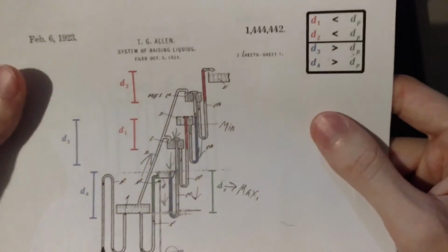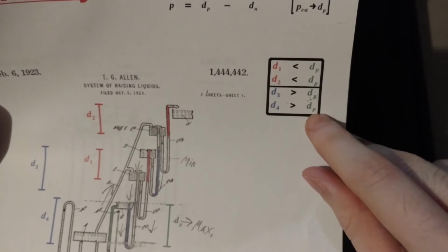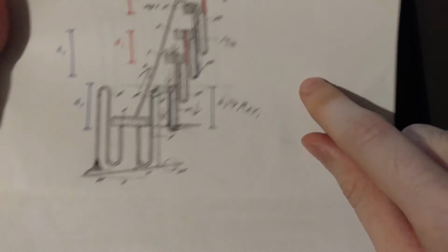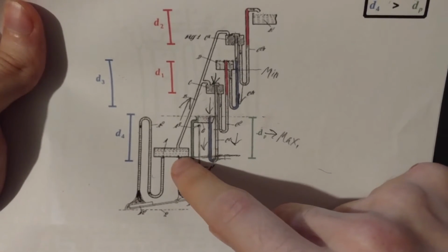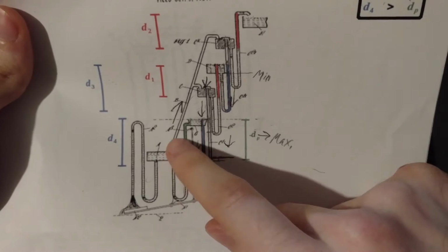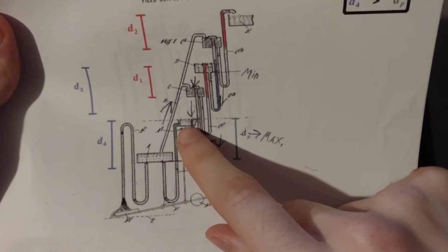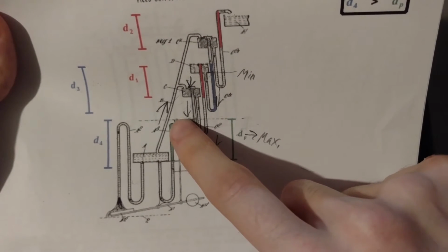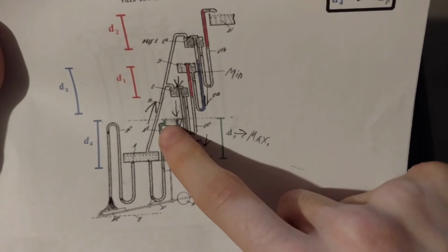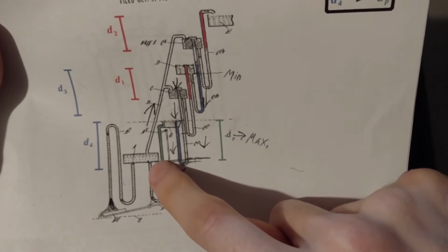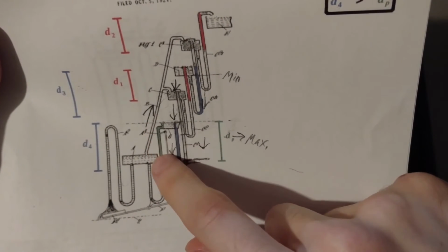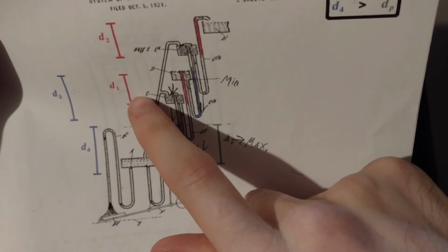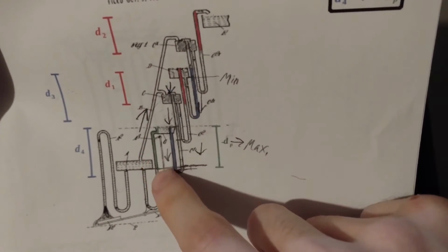But anyways, your pressure in this case, your DP, the variable here that's in green, is determined by the distance between the bottom of that operating tank and the water line here in the feed tank. So the pressure from the water here going down, through the screen tube into this operating tank, that's what determines how much air pressure. It determines the pressure of the air going up into this tube here.